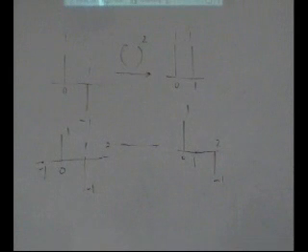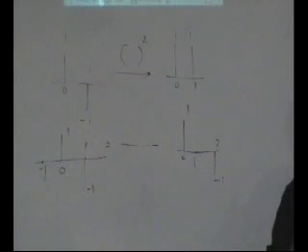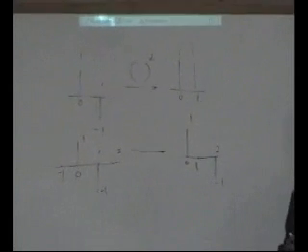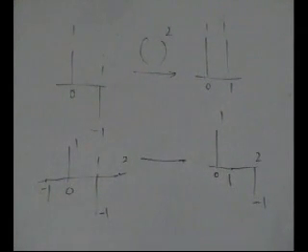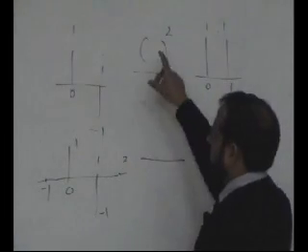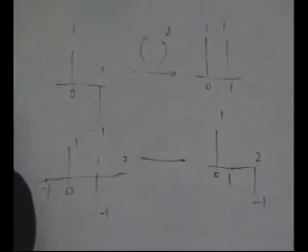Right? I say, okay, you can add, you can subtract. I ask you, add 3 previous samples. Take the current sample, add 3 previous samples. This is a system. Okay? So anything you are doing to your signal is a system. Sometimes you are performing linear operations. So we'll learn about what is linearity.